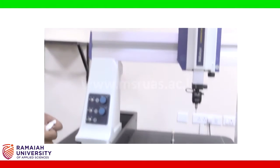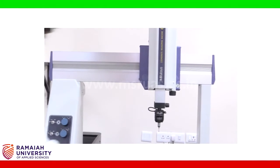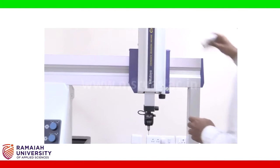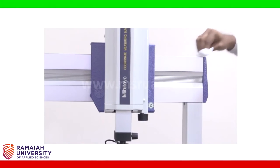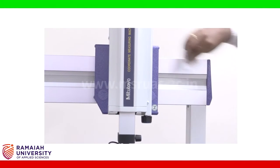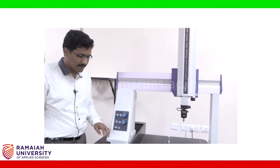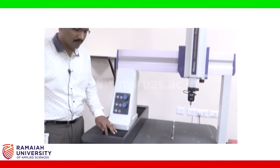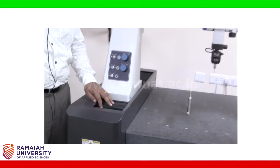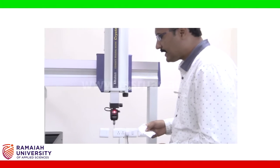Now one part of the x-axis is cleaned, the other side we will clean next. One cannot clean the y-axis since the y-axis is within the machine, so cleaning of the y-axis is difficult and not usually practiced before measurements. Now I am cleaning the z-axis.